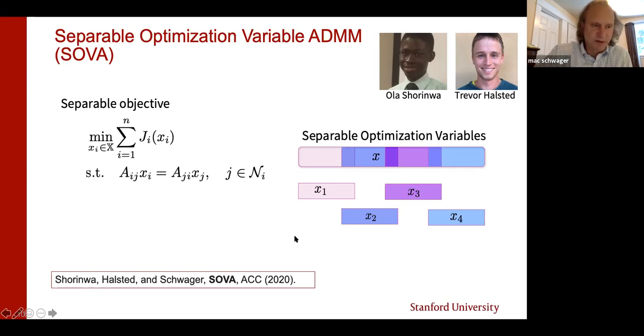The same kind of thing applies, for example, to distributed pose graph optimization or distributed SLAM. If I'm associated with one pose, I don't need to copy the entire pose graph. I only care about maybe my pose and the poses of my immediate one hop neighbors in the pose graph, right? So it's just really a small local neighborhood of all the decision variables.